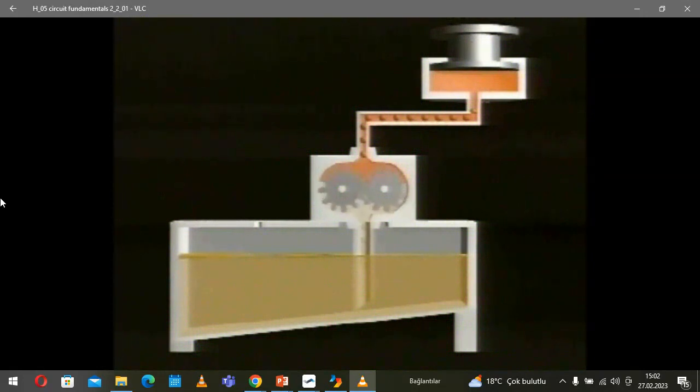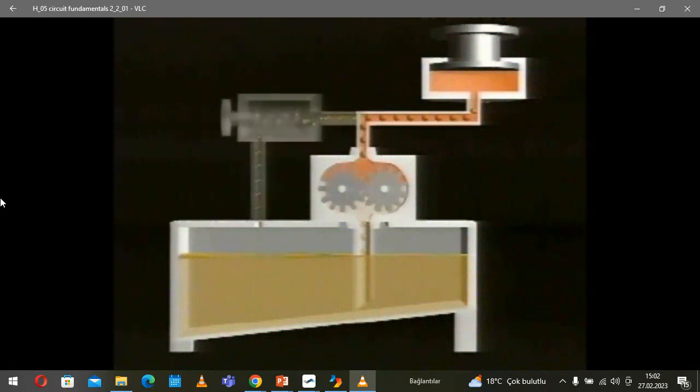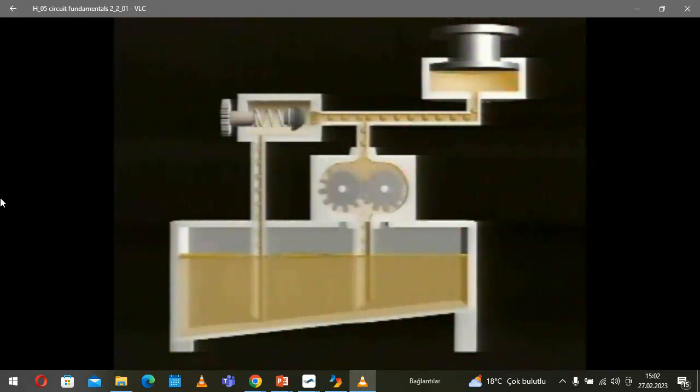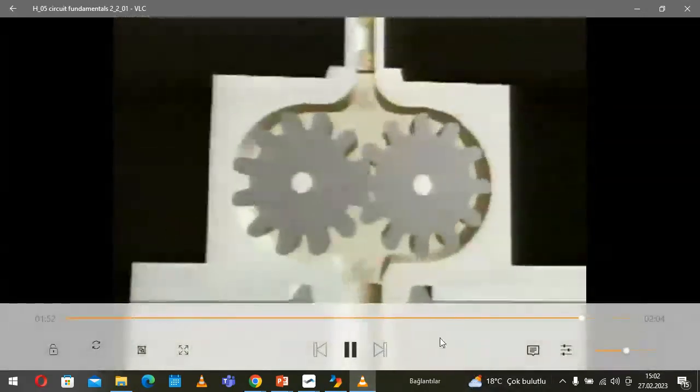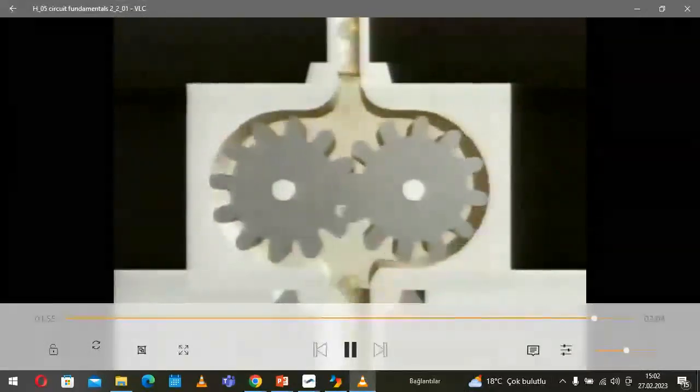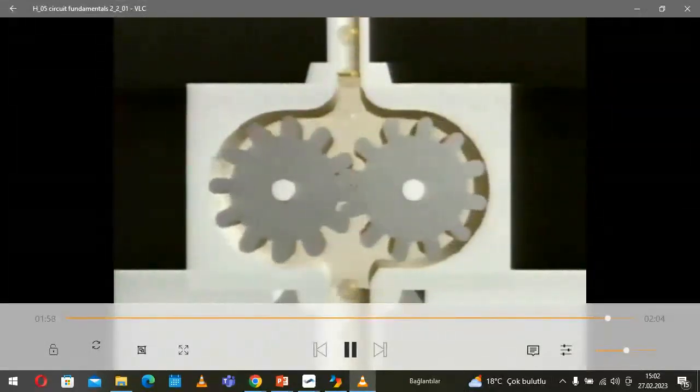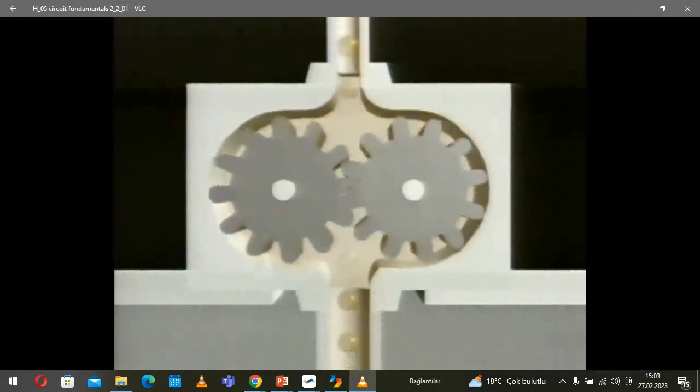If the pump continues to supply fluid and pressure continues to rise, something will eventually have to give. Either the line will burst, or the pump or cylinder will be damaged. This is prevented by a pressure relief valve, which is set to the maximum pressure of the pump. It doesn't open until this pressure has been reached, at which time it channels the hydraulic oil back to the tank. It's usually combined with a pressure gauge to form a unit. The external gear pump generates a constant flow rate because delivery rate is kept at a fixed quantity by the gaps between the gear wheel teeth.